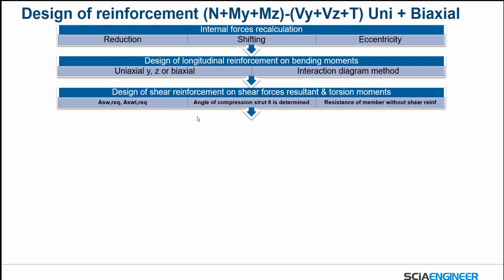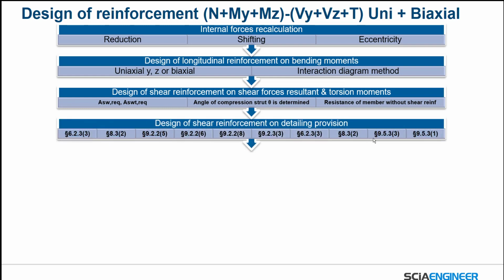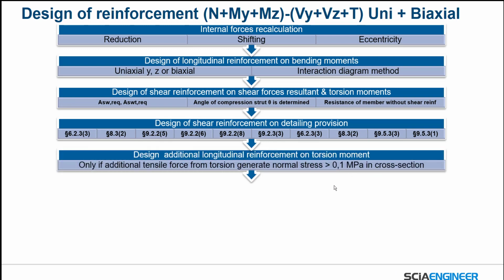Then SCIA checks the shear reinforcement, and we have a very nice feature regarding the calculation of the angle of the compression strut, which is automatically implemented in SCIA Engineer by making a kind of iteration to find out what is the best angle for the calculation. All these articles from the Eurocode regarding the shear reinforcement have been supported.